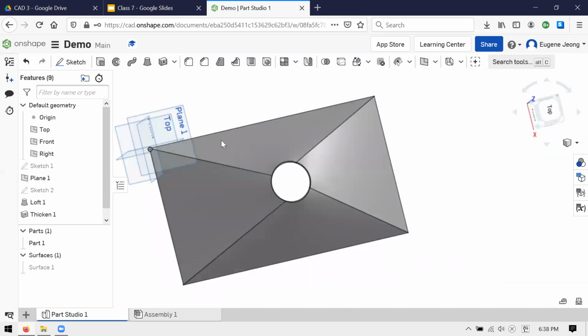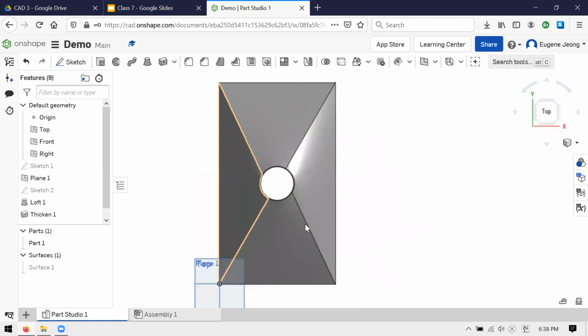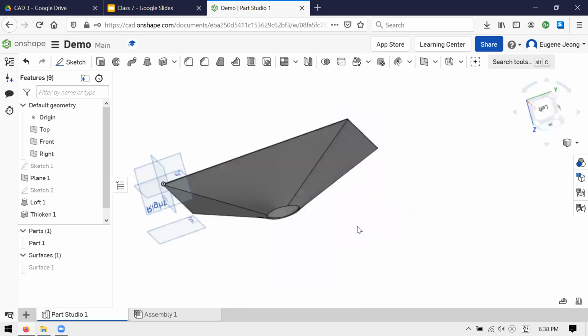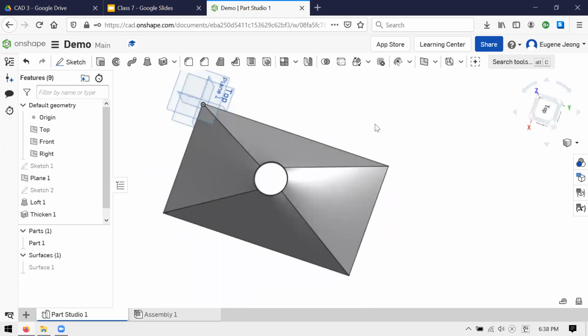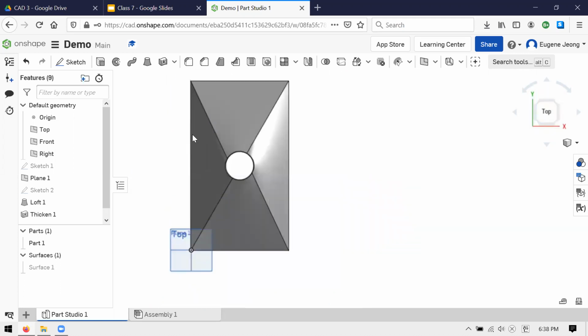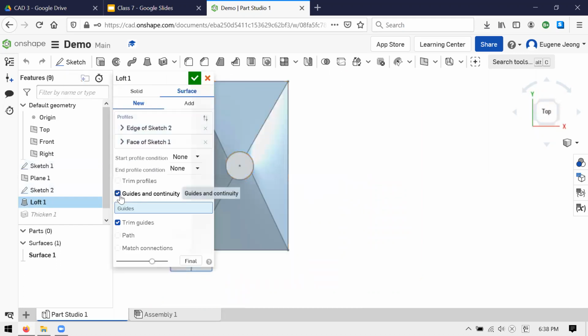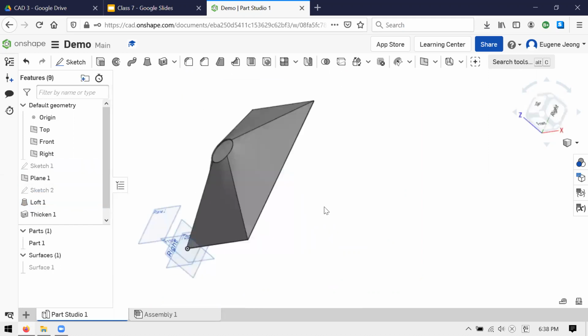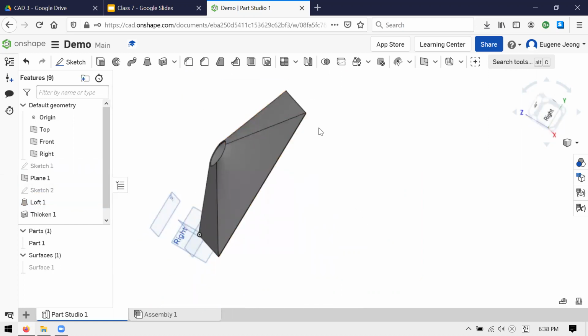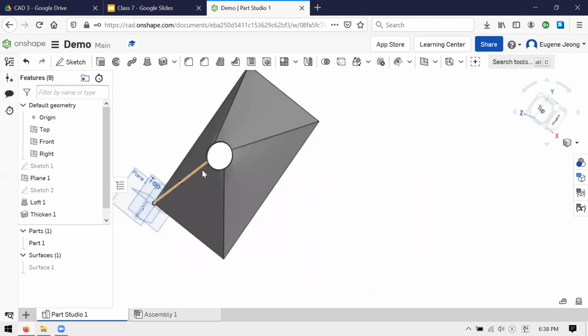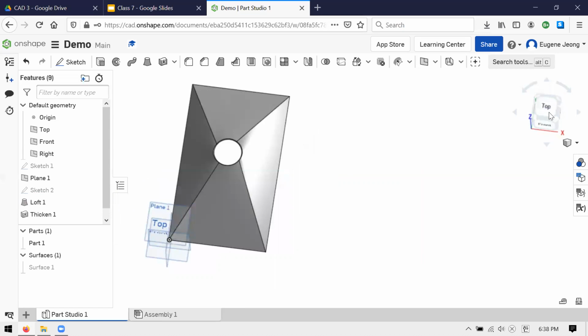Those of you who are more perfectionist may have noticed these lines aren't really radially symmetric, or perhaps they are. You'll notice that this doesn't look that great. What you can do is, in the loft feature, there are these things called guides. So if you were to make another sketch with a line that exactly goes from the point on the circle to the rectangle where you want this curve feature to follow, then you can explicitly force it to do something.